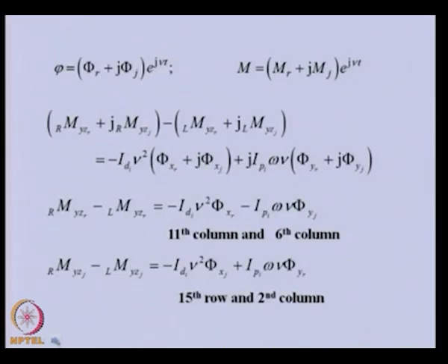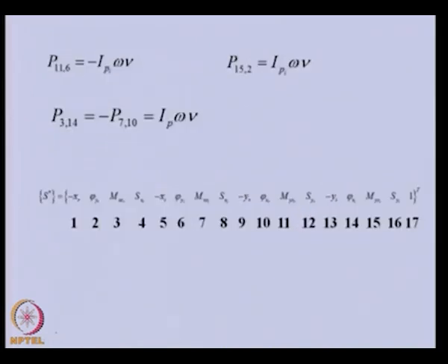So, let us see how the state vector will be represented in this particular case. This is the expanded form of the state vector. Basically, the transpose of this will give a column vector. Here we can see the x displacement, the real part of which I am stacking first, then the angular displacement about the y axis, the bending moment in the zx plane, and the shear force in the x direction. All these correspond to the real part of the state vector.